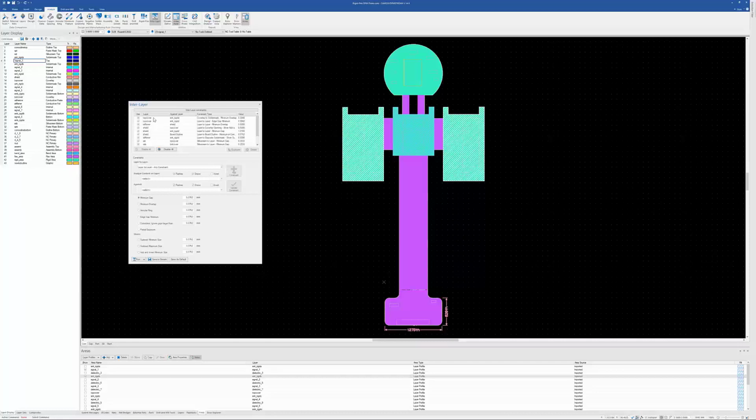So for instance, this first one is looking at the top cover lay to a solder mask layer, okay, with a value in there. There's some additional ones from the top cover lay to a solder mask layer, or a stiffener to a shield. You want it to overlap or not overlap.